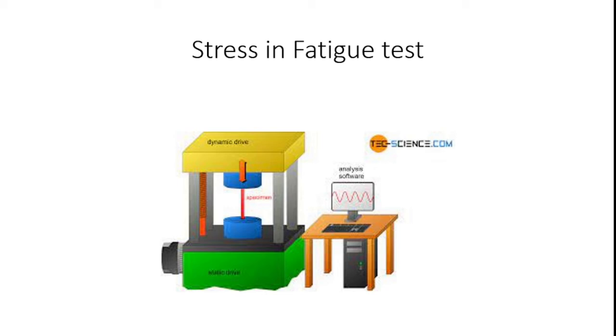The ratio between those extremes is called the stress ratio. This ratio for fully reversed stress becomes minus 1, because compression stress is always denoted with a negative sign.